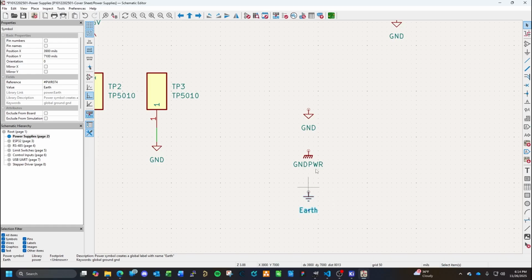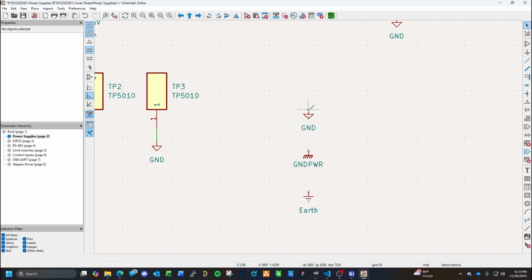So you typically have your signal ground. This is basically your local power supply, like your 5 volt, your 3 volt power supply, the 24 volt coming in from whatever power supply it's using. This is basically your electronic local power supply.